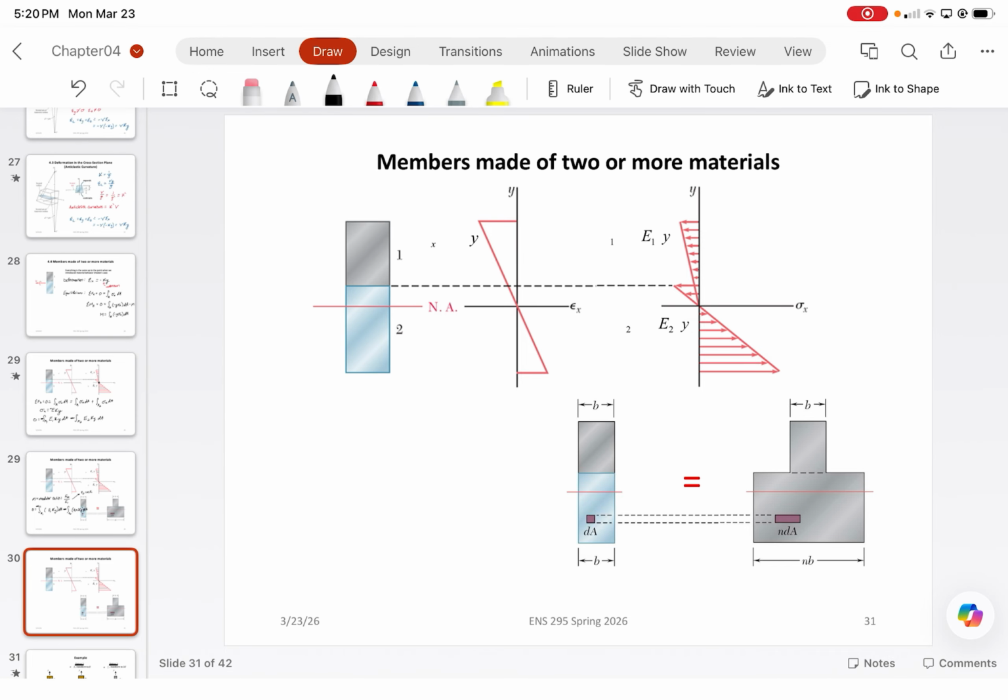Now, if we were looking at this, where might be a good location to do the sum of the moments to determine equilibrium? The neutral axis. I would prefer the neutral axis, because then everything is just with respect to a point of known value. So we could do the sum of the moments about the neutral axis. This is, of course, the moments about the z coordinate.